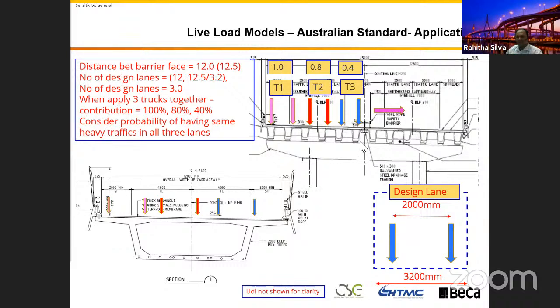In another case you can look at, if you don't have any load on your right-hand side or outbound lane, or if I call inbound lane, but you put all the maximum load on the left-hand side, what you are shown in this diagram, it will produce maximum unbalanced moment in your column substructure, that couple, right? So because of that, don't let the computer program give you all these hundreds of thousands of loads running on your bridge and decide what is the maximum effect on your bridge.